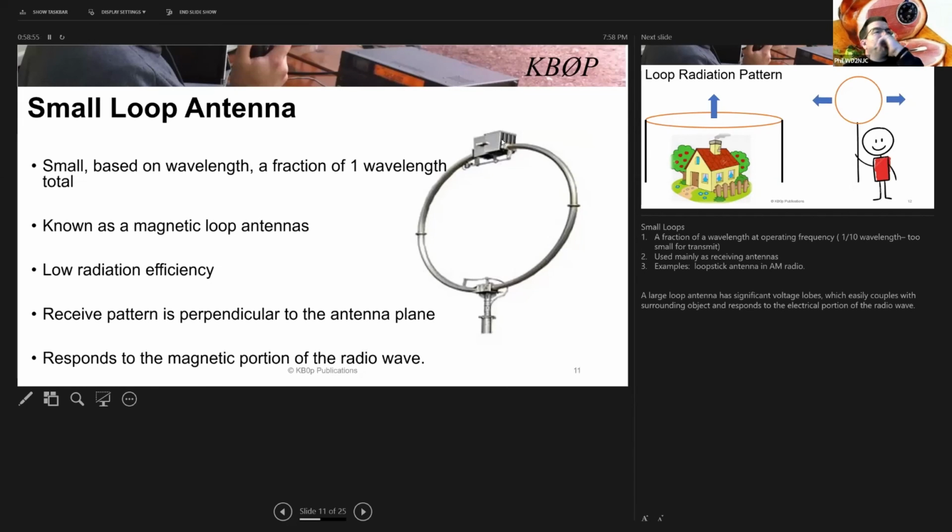I got a question, Paul. You were saying that this is like a high Q tuned circuit. Is that kind of like the theory in the duplexers? Yeah. So what Q is referring to is quality. So you could have a high Q circuit and a low Q circuit. A low Q circuit is a low quality circuit, a circuit that is very broad banded. It'll cover a wide range of frequencies, but it's low Q, so it may not be as efficient.